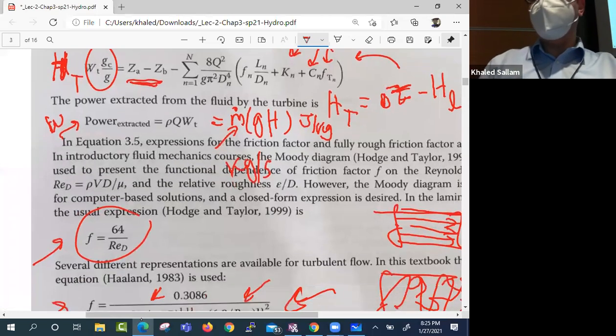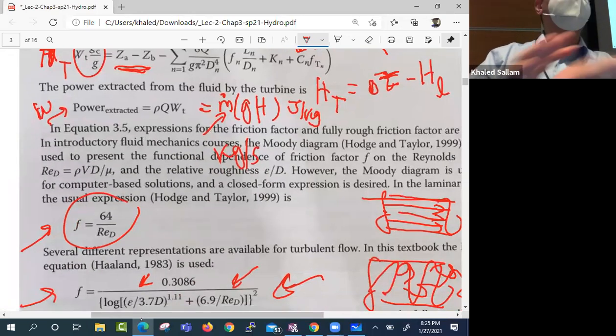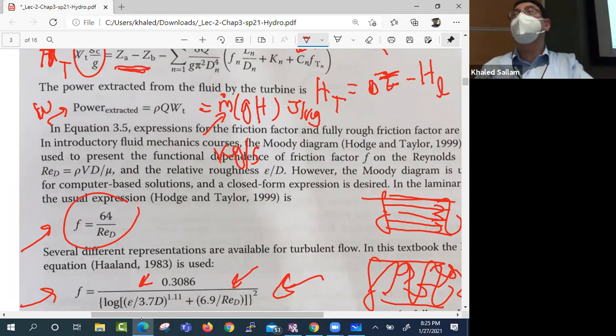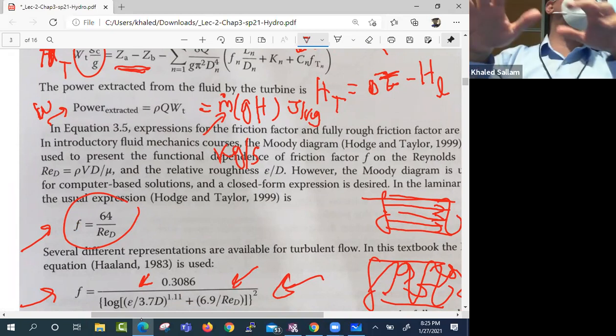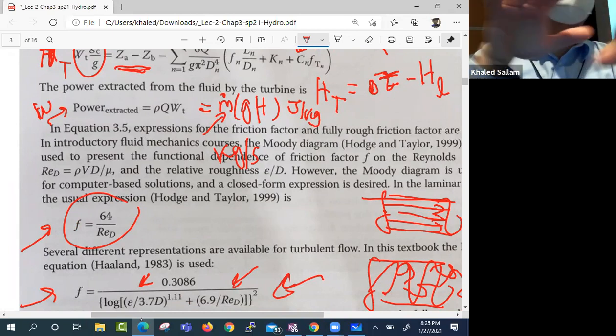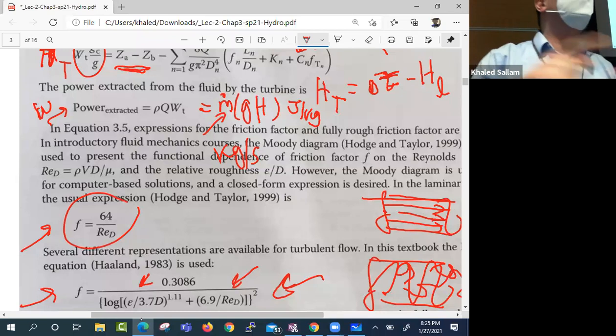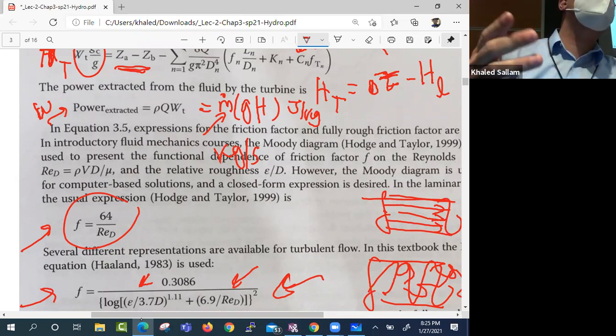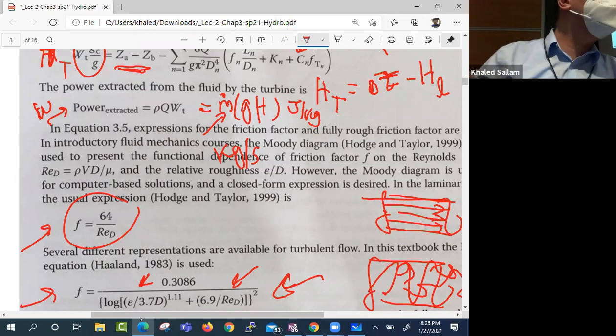So when I was an undergrad, my senior design project was designing a big crude oil pipeline that goes from one sea, the Red Sea, to the Mediterranean. We spent almost 2 months accumulating all those friction factors for different valves so that we could make a database for our program. We made a program that could actually design the pipeline by itself. But we needed all the fittings for all the valves and elbows and stuff. So you collect those things and you can see the different ways that people characterize the pressure loss in their fittings.